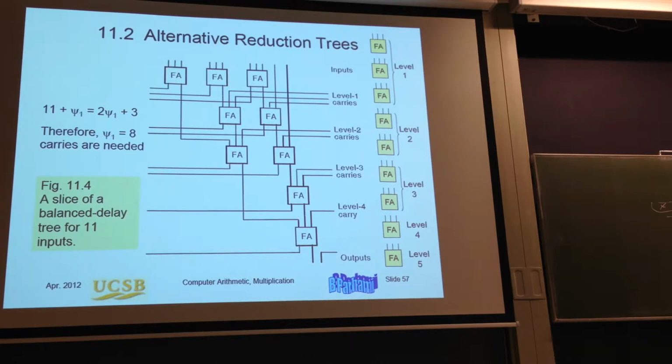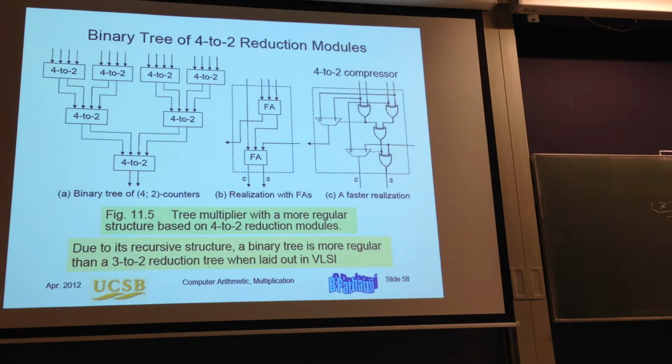And remember, we are talking about 4 to 2 counters, which are very nice for this. I was looking for an implementation of the 4 to 2 counters, and I saw it somewhere, and this is where I saw it. If I rely on population counters, normal counters like full adders or 7 to 3 adders, we had a discussion that I am getting n inputs and producing log n results.